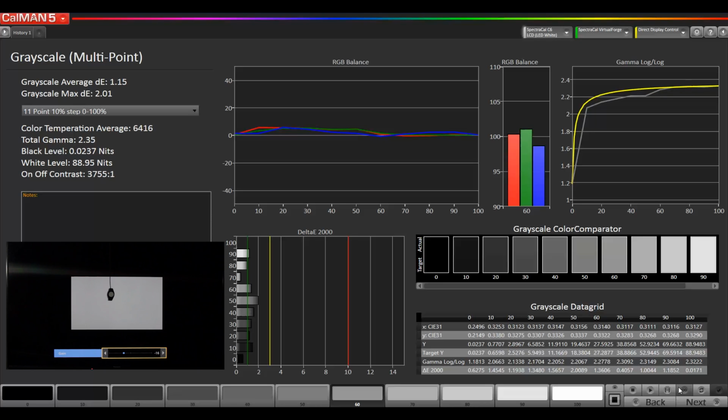and as you can see here in the RGB balance chart, as I'm fixing the gamma, I'm also fixing the RGB balance, and these are all interrelated. When you balance red, green, and blue, all you're doing is you're fixing the chromaticity of the color. You're just making the red, green, and blue balance to that particular white point. But in order to also get it to correct for the luminance level, you need to adjust the gamma. So each particular point has a specific place based on the display's measured white and measured black, and that's because we're using the BT.1886 gamma formula.